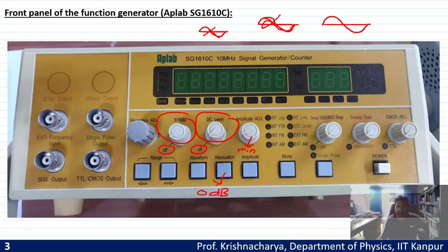Frequency, anyway, you will be reading which range, so you will not be confused. But for example, if you don't pay attention and suddenly this 40 dB attenuation is already on, you will always be assuming that you are giving the full signal, whereas actually you will be giving 1/100th of the signal. So to avoid the confusion, make sure that this is your initial setting.